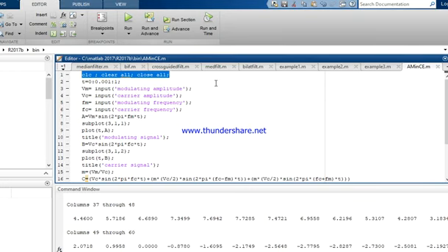For these four inputs, modulating amplitude, carrier amplitude, modulating frequency and carrier frequency, we also require the time period, in the output as well. So in the second line we set the command t equal to the time period, from 0 to 1, that is 0:0.001:1. Basically we assume the time period t from 0 to 1, and the subdivision of the time period we put as 0.001. Understood?